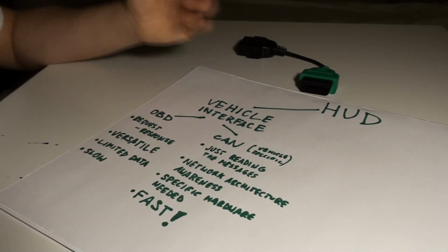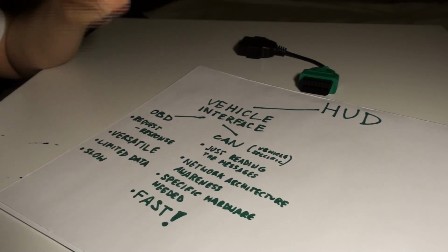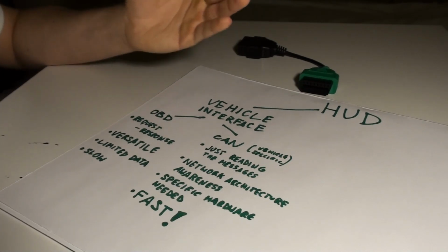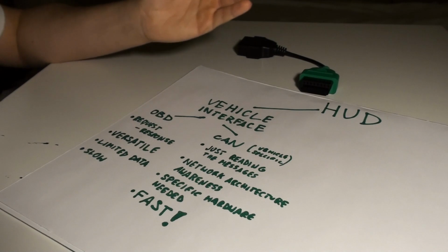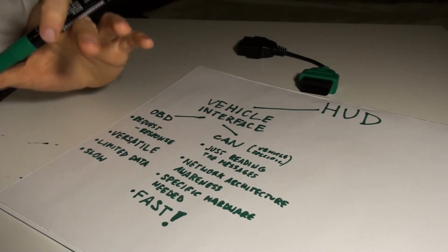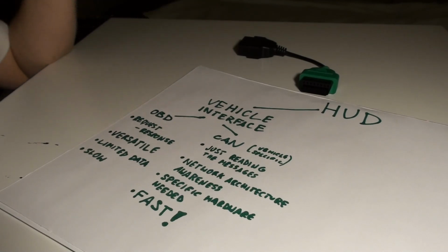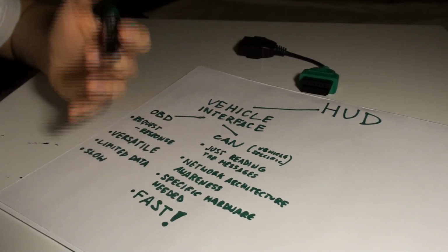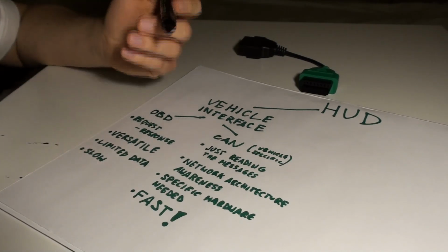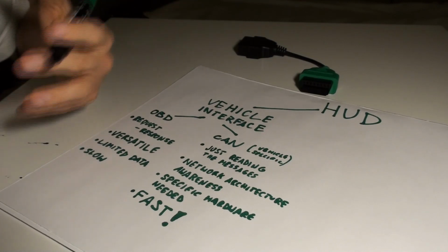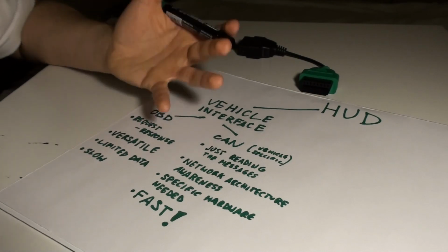It's a bus that integrates the communication between all of the interior components of that particular car. All the powertrain data, which I'm especially interested in because it's vehicle speed, engine speed, fuel level and so on, is received by the body computer over some different network, and then the body computer broadcasts this data to all of the nodes that are connected to that fault tolerant CAN. So this means that the gauges in the car, those factory gauges, are just reading the car's speed, engine speed and so on, and they don't need to request anything, which makes this process fast. That is also a good advantage for such a project, that it's going to be fast and it won't require much time to process that information and to display it on the screens that we're developing here.